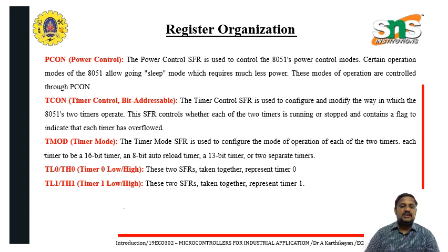Another one is TCON, the timer control register, which is bit addressable. This SFR configures how the 8051 timers operate. It controls whether each of the two timers is running or stopped, and contains flags indicating whether each timer has overflowed. The TMOD register, the timer mode SFR, is used to configure the mode of operation of each of the two timers.